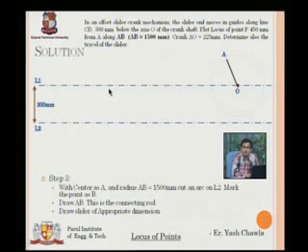That's why we took the radius equal to the connecting rod and cut an arc on the line on which both were oscillating and rotating. Between that problem and this problem, there is only one difference. Instead of cutting the arc on line L1, we are going to cut the arc on line L2. Why? Because my slider will be reciprocating on line L2.